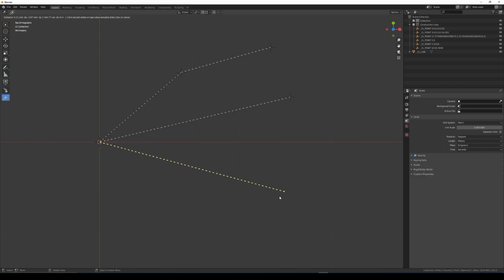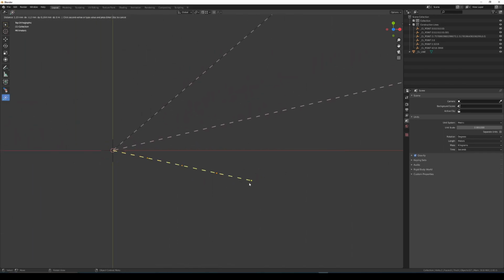So if you hold down Control whilst you drag your guide edge out and use the mouse wheel, actually if I zoom in a bit you'll be able to see a bit clearer, you'll see these orange dots, and they show that the guide edge will be divided perfectly at those particular points, and you can reduce or increase the number either by holding control and using the mouse wheel or using the up and down arrow on your keyboard.